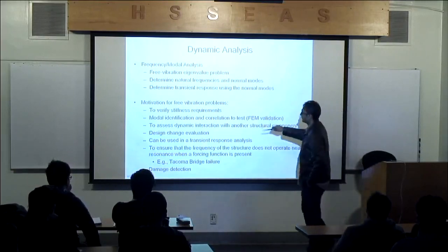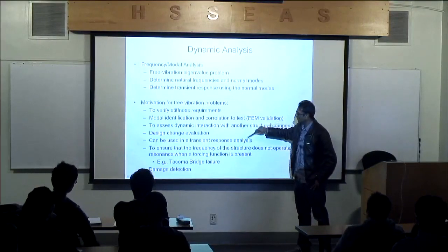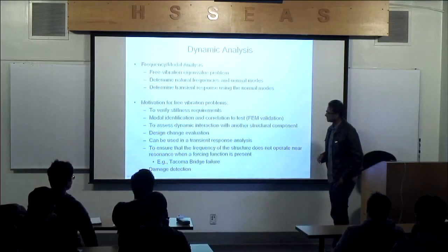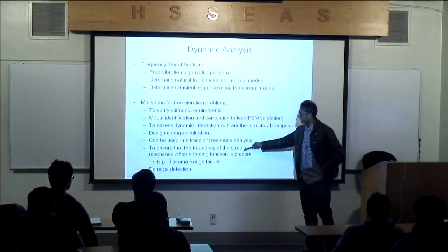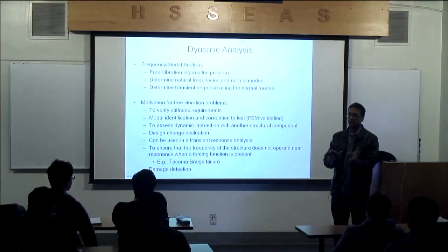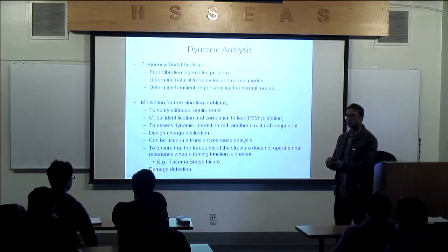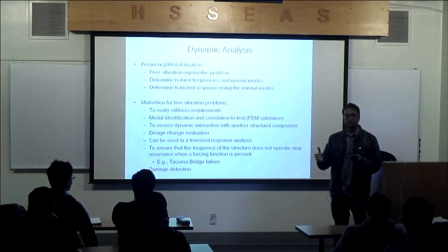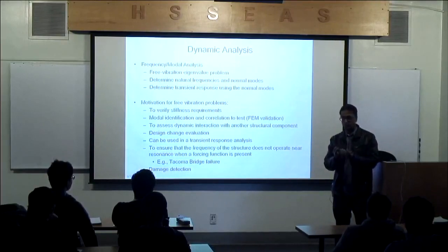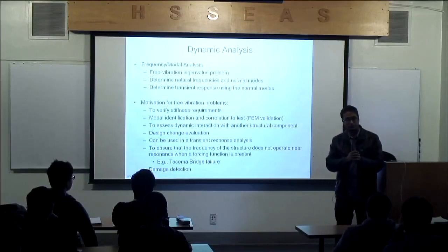We can also use free vibration problems to analyze transient response, and that's a lot of what we'll be talking about. We can also look at designing the structure so its frequencies are far removed from the excitation frequencies. Because if the excitation frequencies I put into the structure coincide with the frequencies of the dynamic characteristics of the structure that you're looking at, you can have a resonant condition. Don't you agree?